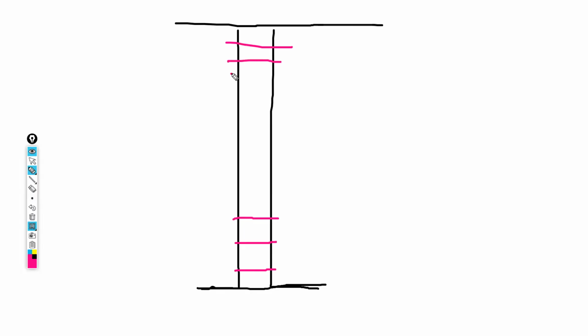We have those links closely spaced. As you go towards the center of the structural element, the spacing increases. Then as you turn towards the support region, you have them closely spaced. But then on site, it is on a rare case that you find something like this.